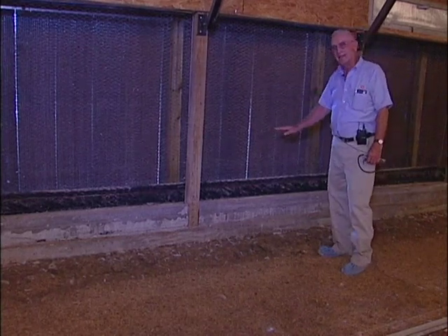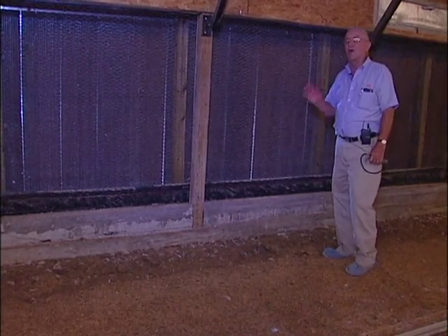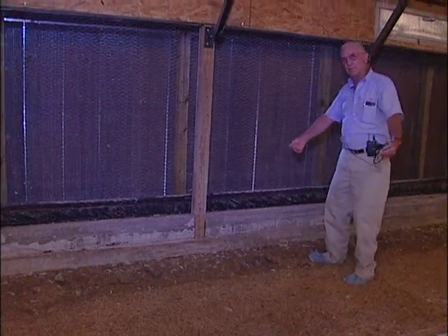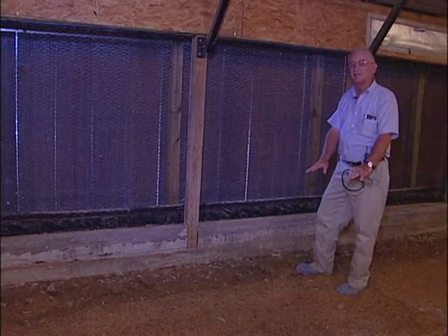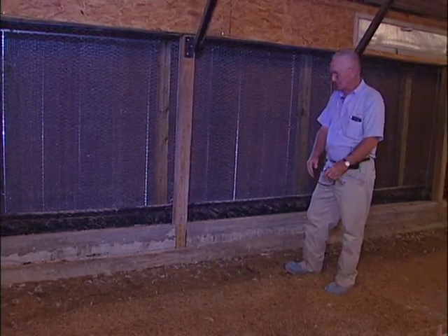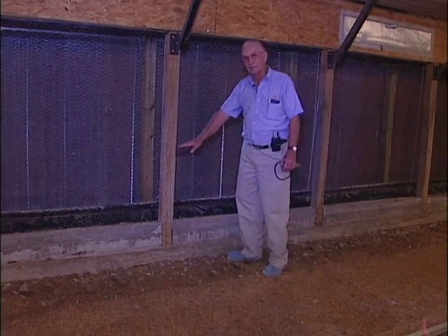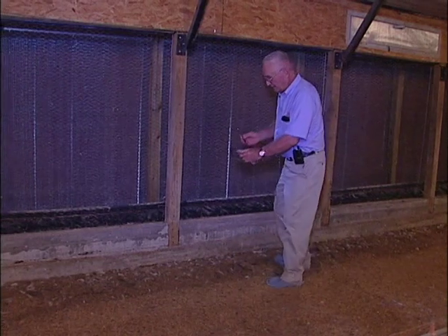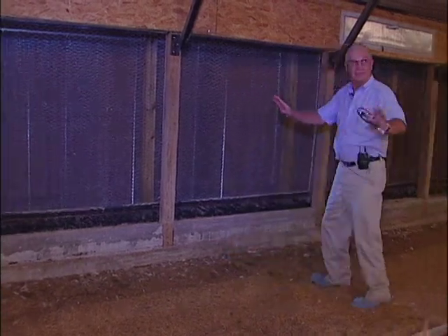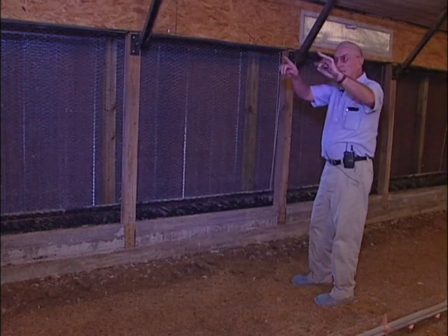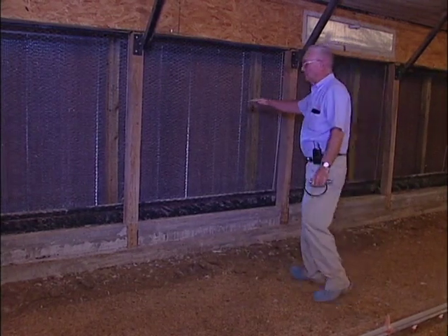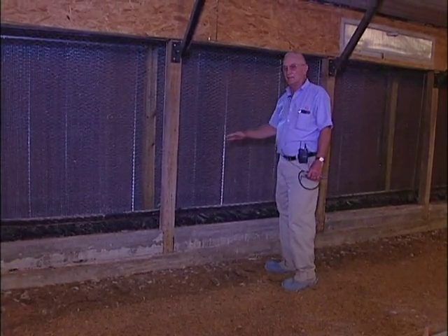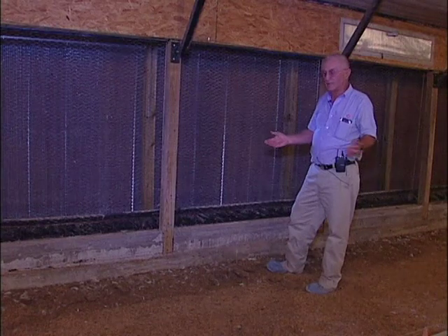So when the curtain is allowed to be open all the way to the bottom, or the curtain is open from the bottom up, then we've got too much airspeed that comes in on the chickens in this area of the house. So we don't ever want the curtain to be lower than 3 feet from the floor. Now, we'll also look based on the surface area of the pads compared to the fan capacity. In this case, the inlet curtain probably should never be open more than about 36 inches.